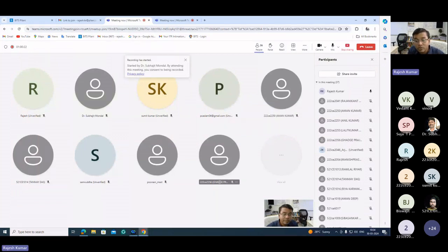Any member, if it is subjected to compressive loads, you have to take care. Whenever we have tensile loads, there is no problem in the stability. Wherever the member is subjected to compressive loads, you have to see whether this member is stable or not. So how to avoid that loss of stability? Increase the thickness of the members, or give some stiffeners at discrete locations to avoid this phenomenon.